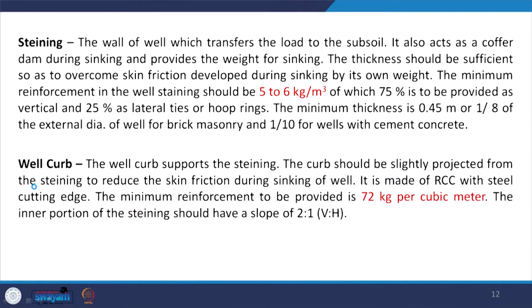So, well steining is shown here, and it also acts as a cofferdam during sinking and provides the weight for sinking. The thickness should be sufficient to overcome skin friction developed during sinking by its own weight. So, what will happen? When you sink the well inside the soil, due to the heavy well itself, it should not happen that the side wall or the well steining collapses.